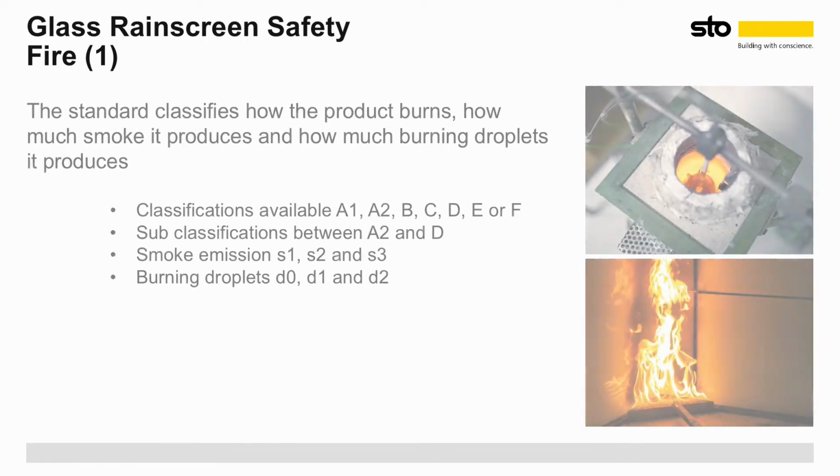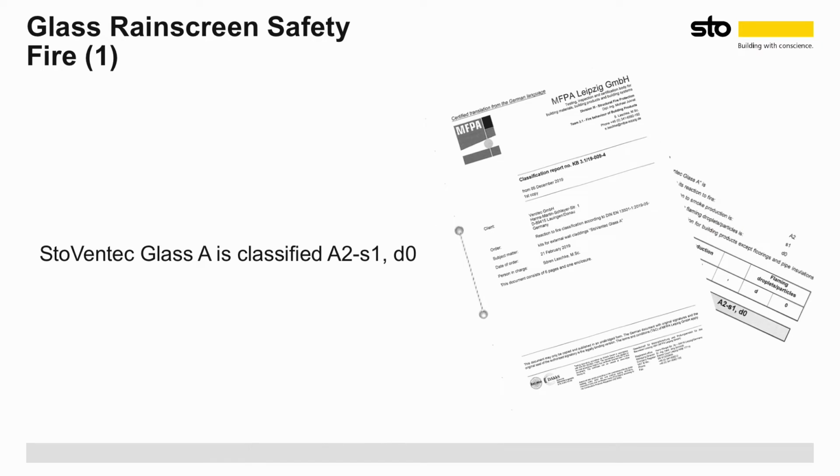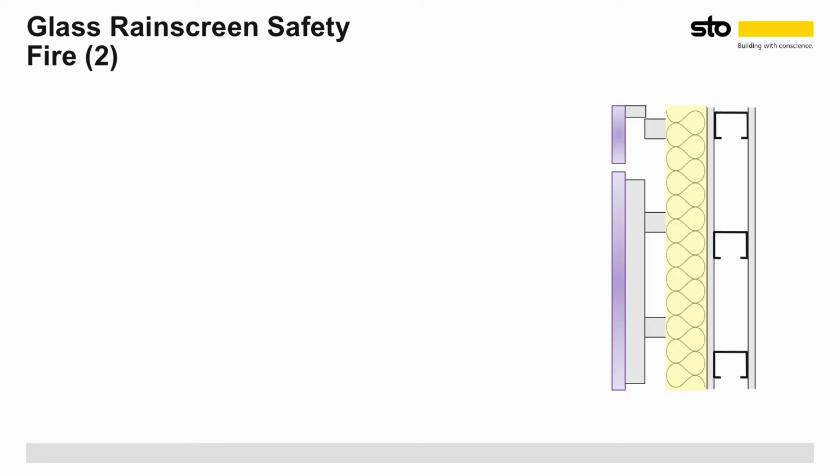Cladding specified on a multi-storey building must not appreciably accelerate the rate at which fire will spread up the building. Fire breaks must be designed to work in conjunction with a particular building construction and cladding system. They must provide a barrier to fire and close the cavity in a fire event. Seek the approval of the fire officer and building control officer for all matters concerning fire break design and strategy. A typical section detail showing a fire break rail is shown here.